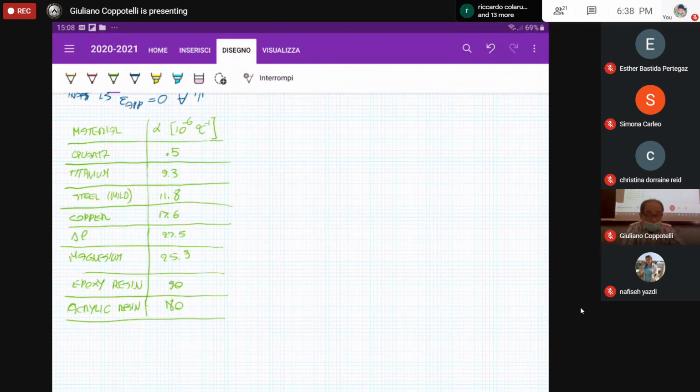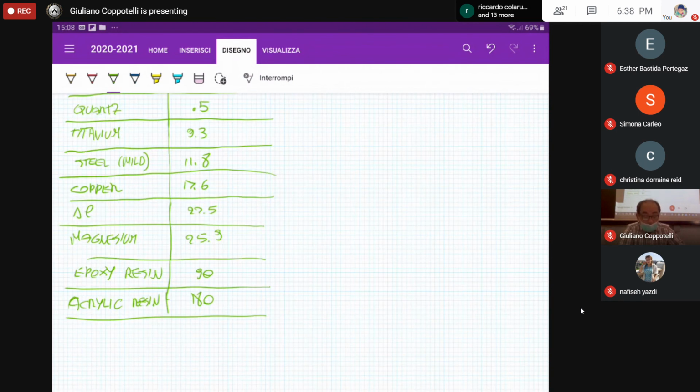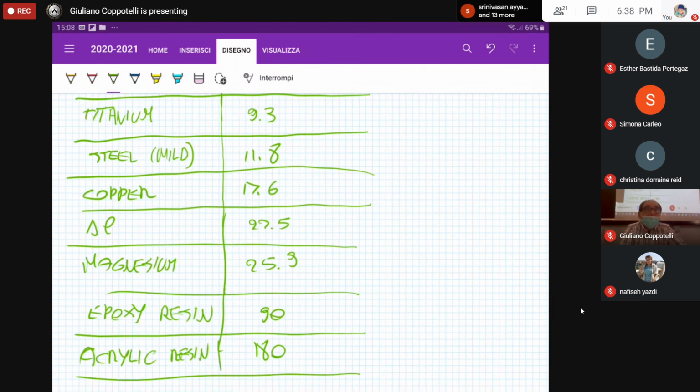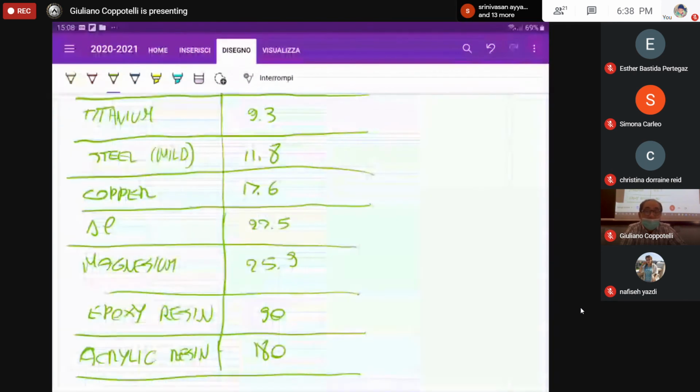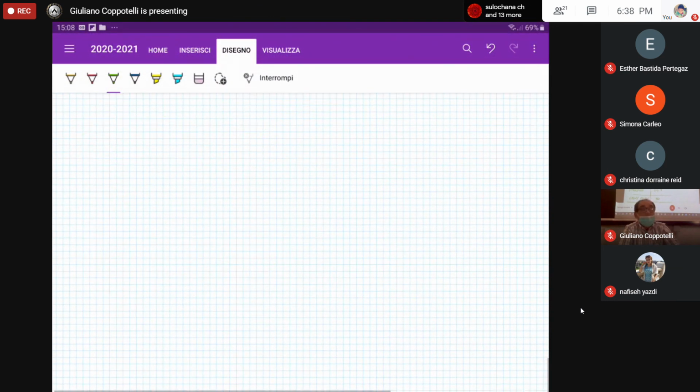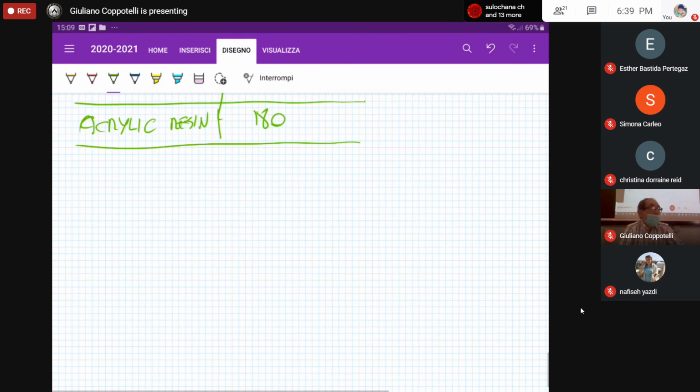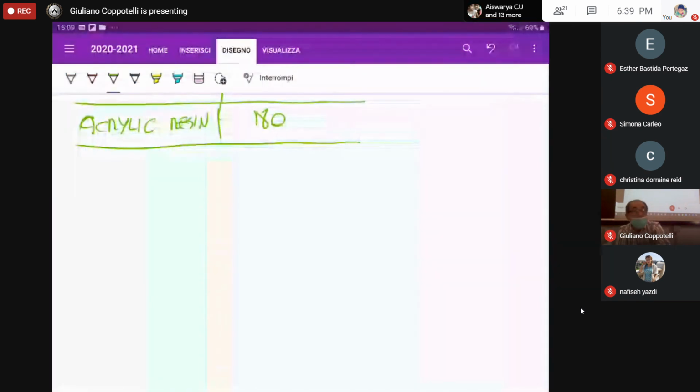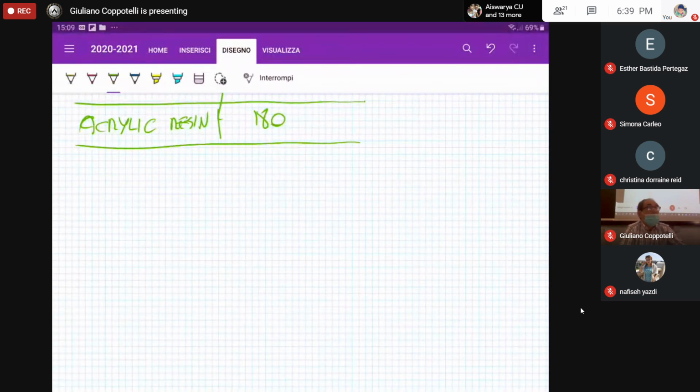Generally speaking, in addition to that information, that is the chance of having self-compensating strain gauges, the manufacturer is giving you a chart that takes into account all of this. So you can compensate for thermal effect in your measurement just using this chart, without knowing any formula, just knowing the operating temperature.